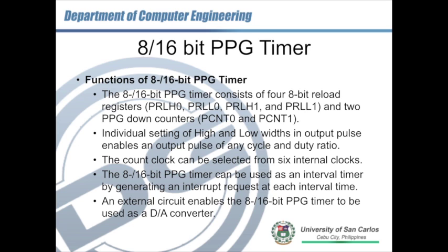As I introduced you to the Fujitsu MB90F387S, one of its most familiar peripherals is the AD converter. So this time, by using the PPG timers, we can also do the inverse of the AD converter by using it as a DA converter.